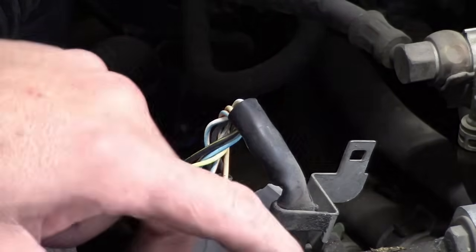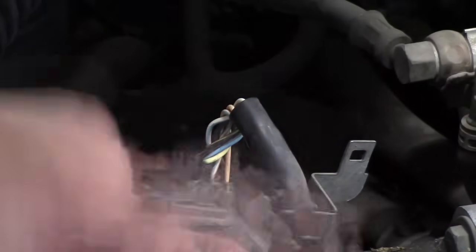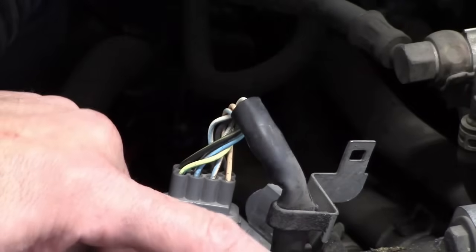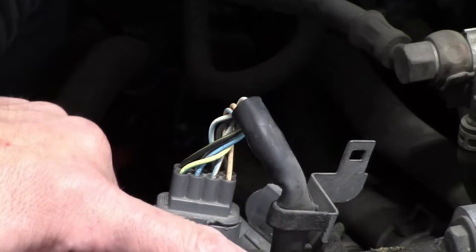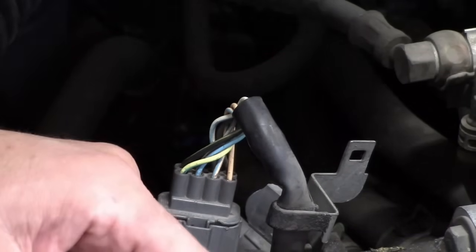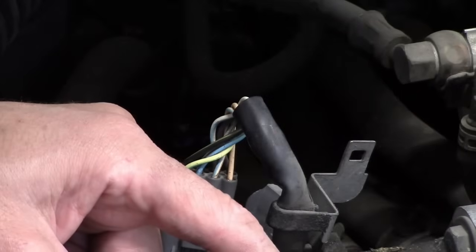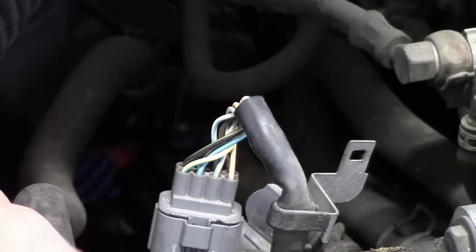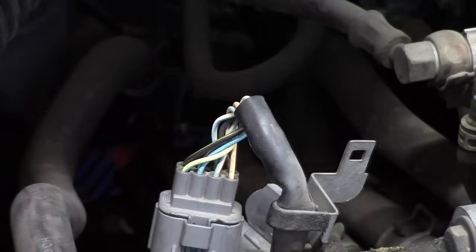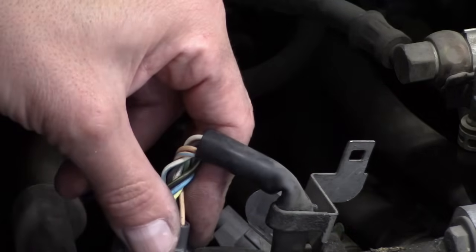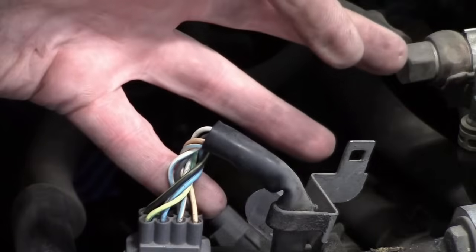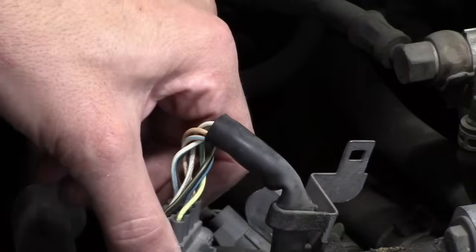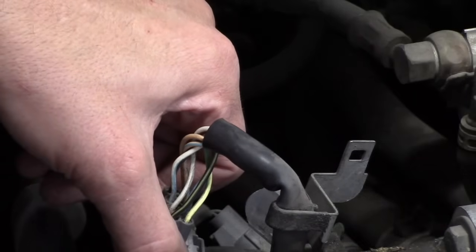The other thing is, again, I am not familiar with this. It still could be whatever the sensor is in here, a camshaft position sensor. This car still may have a crankshaft position sensor responsible for this, but at least if I could get the coil to spark myself, we could rule that out and we know which direction to go. But I can't, this is going to need a wiring diagram because I have no idea why there would be 8 wires here. I honestly can't even fathom that.